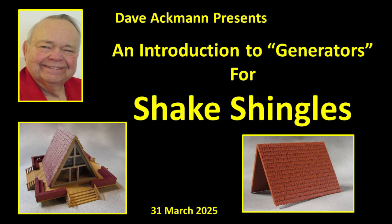Hello, and welcome to this tutorial on creating shake shingles for 3D printing using generators. I like to characterize the end product of this generator as organic, in that each shingle differs in width, height, thickness, angle, and horizontal separation from each other, like I would expect on a roof or wall of cedar shingles, each nailed by hand. The generator makes this possible by allowing you to specify minimum and maximum values for these 5 parameters, and the software then randomizes the shingle attributes within the ranges you specify.